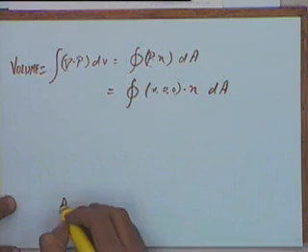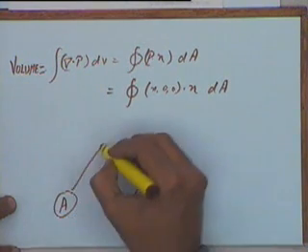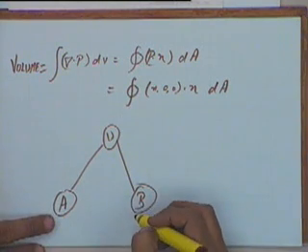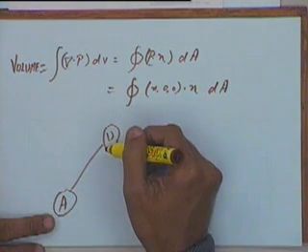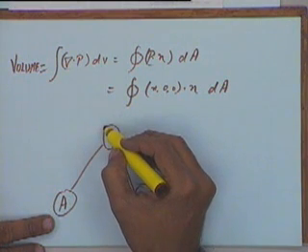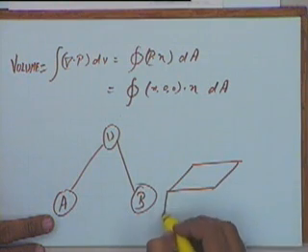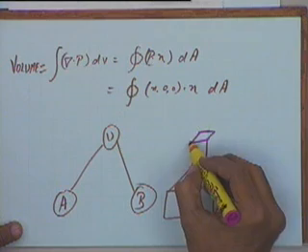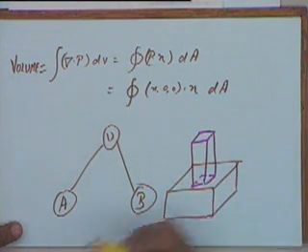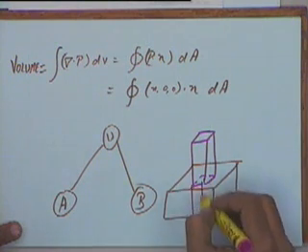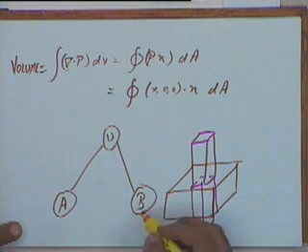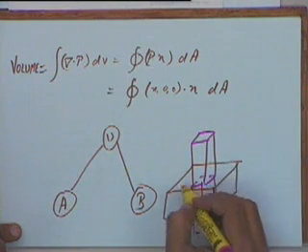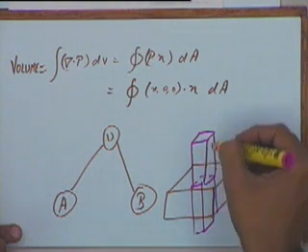Let's say I have two solids A and B. I have done the union and now I have a solid A union B. I know the boundary representation model for A, I know it for B. But if I have to find the volume of A union B, I have to evaluate A union B first. That means I have to get the B-rep model for A union B. Let's say I have one block like this and a second block, something like this. Let's say initially it is longer. Once I do the union, I get this block with a handle on top. I'll have to get the B-rep model for this complete solid, which will be this top surface with a cut in between, these vertical surfaces only up to this point, and so on.